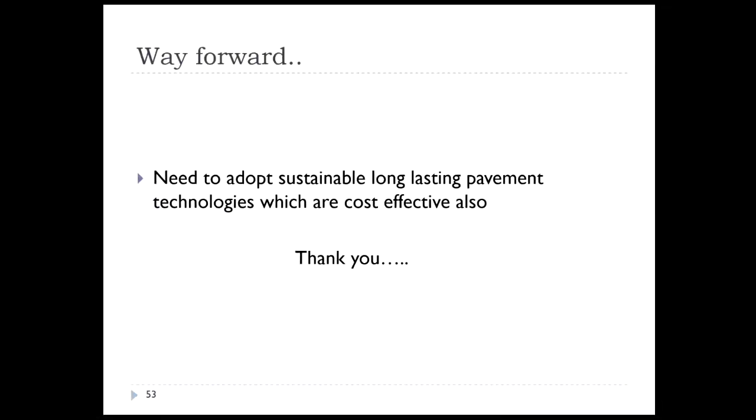So you can consider any of these relevant technologies we discussed today in the class, such as short panel concrete pavements, where you can reduce your pavement thickness by something like 100 mm or even 75 mm by choosing an appropriate panel size.